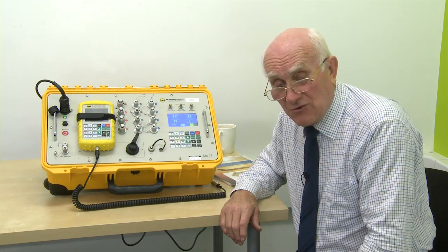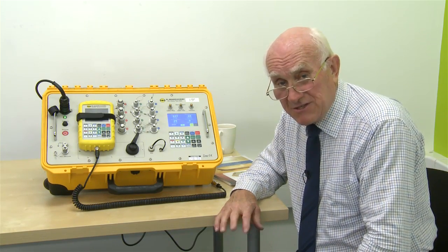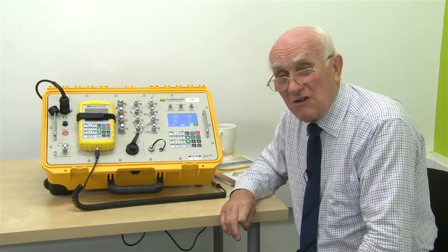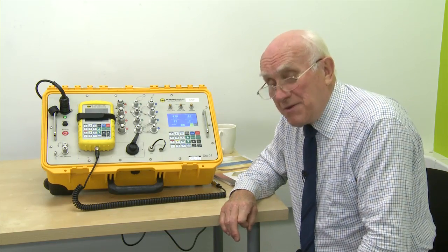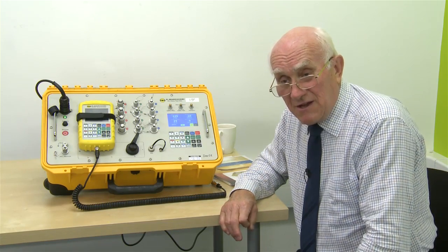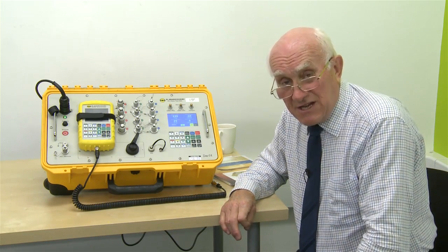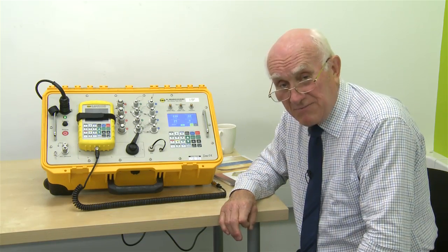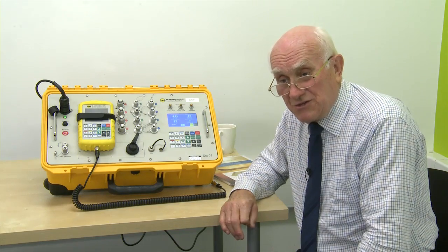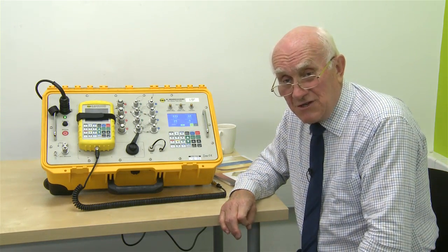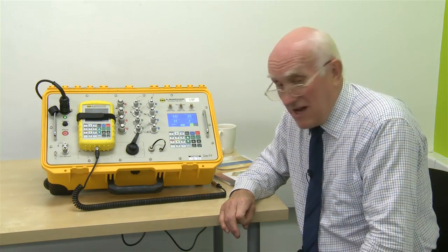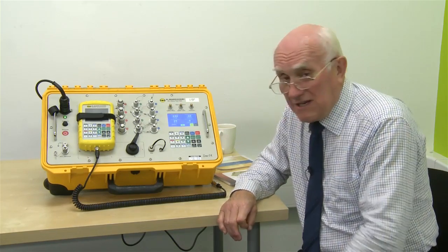is the MPS 45, is a twin channel instrument, a conventional pitot-static altitude and pitot-total for airspeed. The MPS 49, however, is a three-channel instrument. Not only does it have the conventional static and pitot, altitude and airspeed, but additionally a third channel for angle of attack, so that you can check out the more recent pneumatic angle of attack sensors on the aircraft. Here today we happen to have a three-channel instrument.